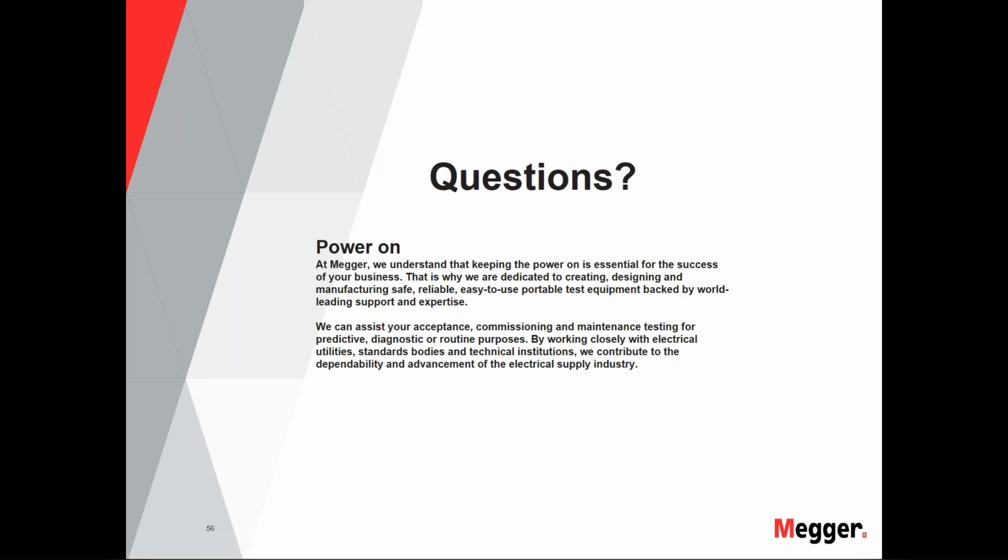Hi, good morning all. In general, the 32 element is used to protect against prime mover loss of power. So when we are in synchronized condition, the prime mover starts losing power. Basically, it's not able to pull at the speed. Then the generator starts drawing current from the system. So the answer to this question is it's the current. We see the reverse direction of the current, and we calculate the reverse power to operate the element.